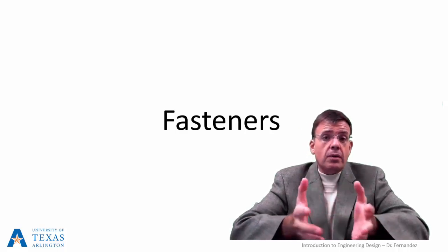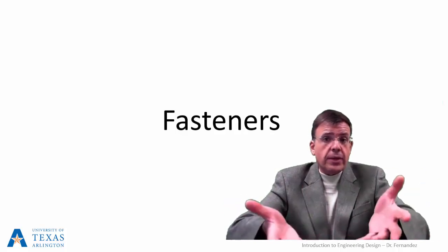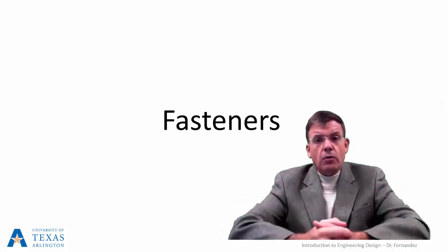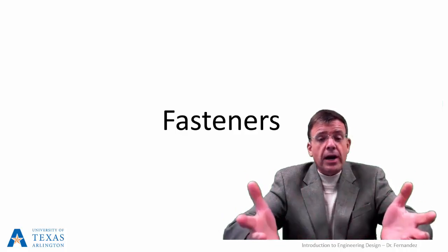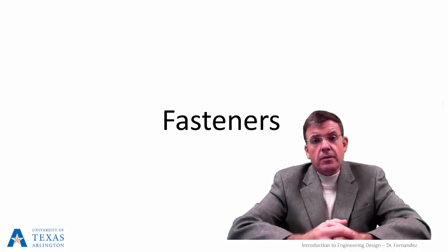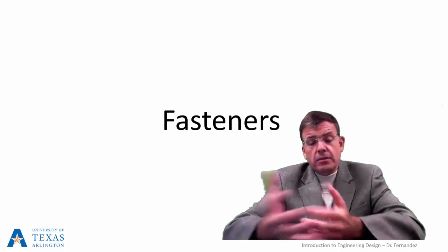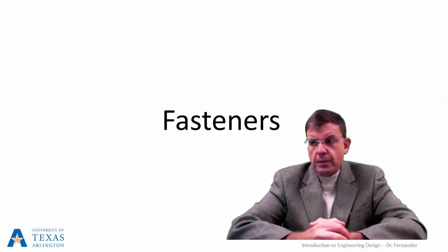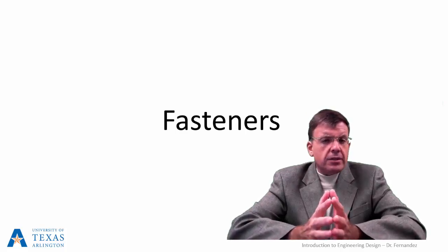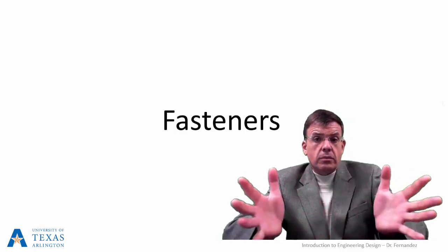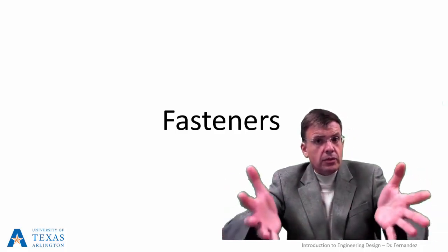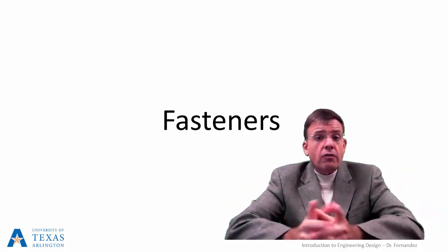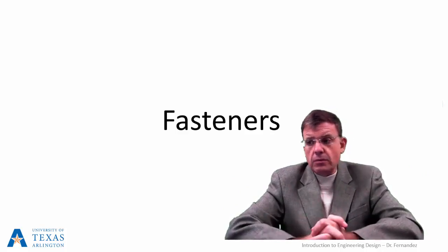Fastening is also a primordial example of commercial off-the-shelf technology, and we've already seen that. And we can go to online catalogs and navigate our way through what truly is a bewildering variety of types of different technologies that can be used, and we've already been exposed to that. Okay. We use fasteners generally when we want to be able to both assemble and disassemble a part. So if we don't want a permanent assembly, then fasteners, of course, is a good place to go. Although not all fasteners are allowed for disassembly, so we'll see this as well.